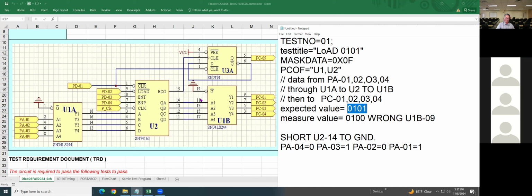In order for the output Y1 to equal the input A1 of U1, pin 19 must be grounded. So that's why you have to check U1 pin 19. If it's grounded, then now you have to change U1.